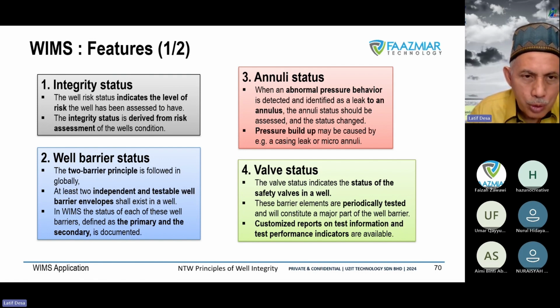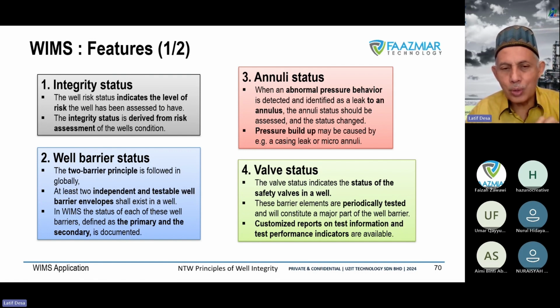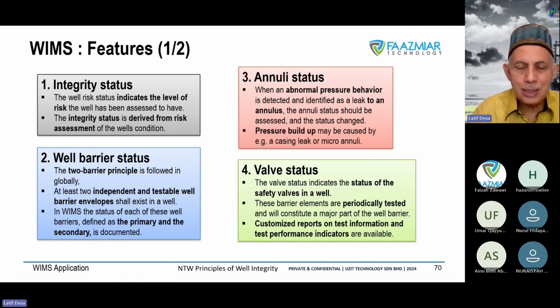At the same time, we're talking about the status of the annulus. We continue reporting, and if there's a potential for annulus pressure going up because of thermal effect, there will be some mechanism like a check valve to be installed, or a squeeze job with cement in the annulus to stop that, or some element of bleeding off continuously. If the pressure starts to be uncontrolled, then we talk about continuously bleeding off the annulus, and putting something like a small line, a kill line or control line, going down below the seabed to release any gas that is continually coming in. So there are a lot of options available, and surveillance will help us understand the steps to put safety protection to the well or to the platform itself.